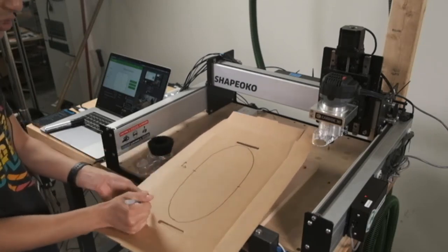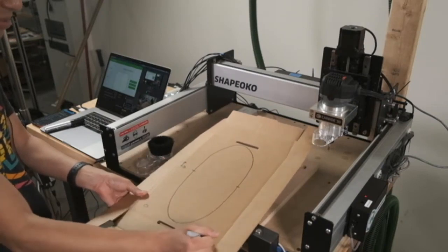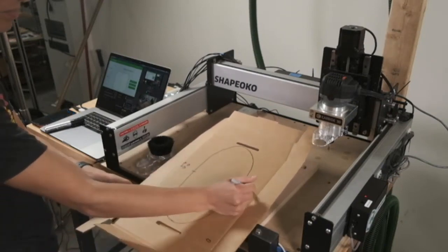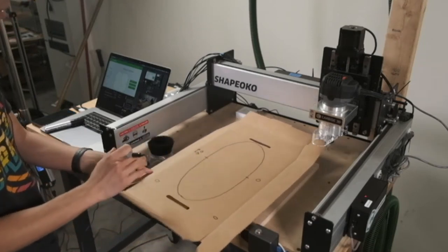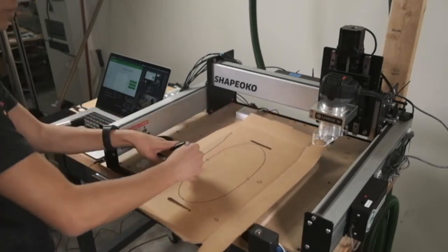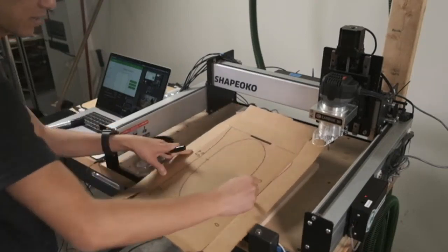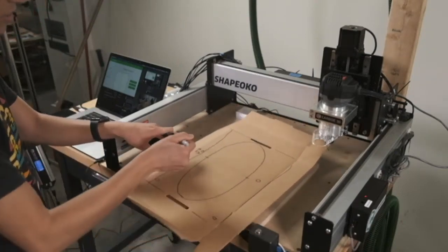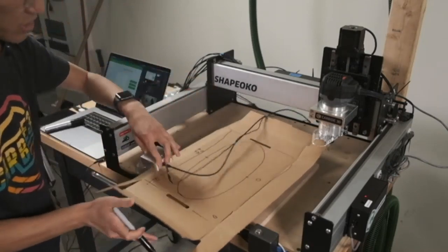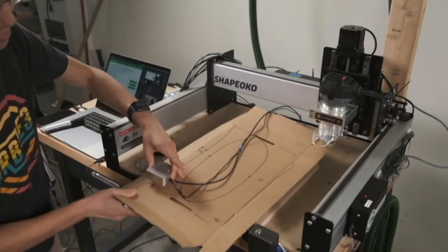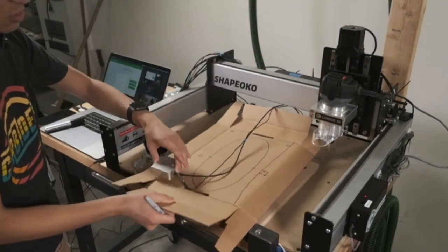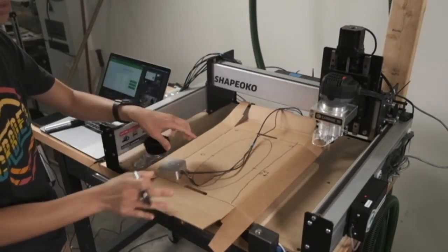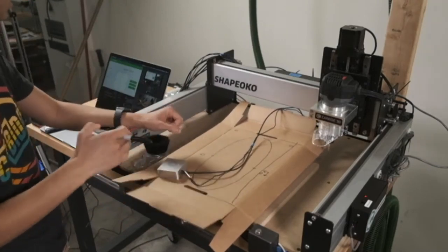Usually, if you can machine some locating pins or features in your workpiece as you're machining these, you can tile this out. Or if you have a perfectly rectangular piece of stock, you could maybe throw a touch probe on the corner, flip it around, and then use a touch probe to relocate this corner so you can machine this half. It all depends on how you're doing it.